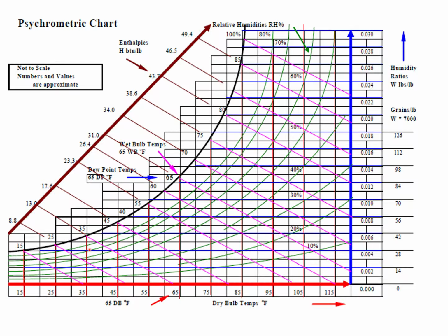Okay, in the meantime, you can see some other vertical lines. These vertical lines are nothing but dry bulb temperature. This determines the dry bulb temperature, and this horizontal line determines the humidity ratio, these values. However, this point of the horizontal line determines the humidity ratio, but this point of the horizontal line determines the dew point temperature. So this is the dew point temperature, this is a dew point temperature. So this line is called the dew point line.